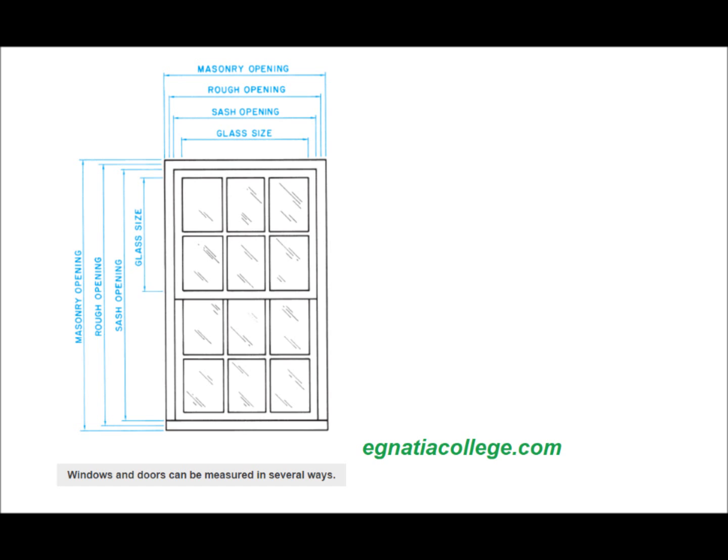Sizes of windows. The sizes of windows and doors are usually shown on a special window schedule or door schedule, but they might also be indicated by notes on the plans near their symbols. Door and window schedules are explained later. The notations of size show width first and height second. Manufacturers usually list several sets of dimensions for every window model. The glass size indicates the area that will actually allow light to pass.